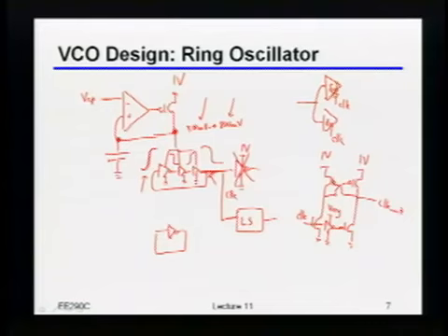They're not balanced. What do you mean? You're right, but what do you mean by that? The duty cycle is not 50%. There we go. The duty cycle is messed up. Okay, why is the duty cycle messed up? Because the drive strength is changed when the regulated voltage is changed for the NMOSs.